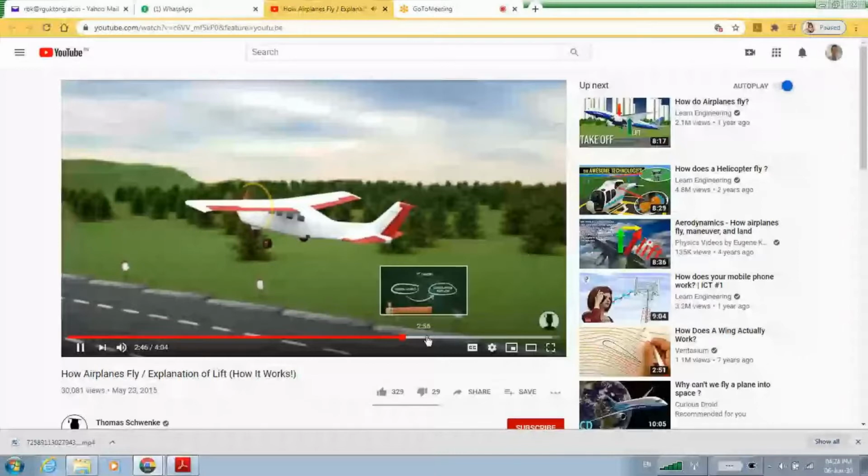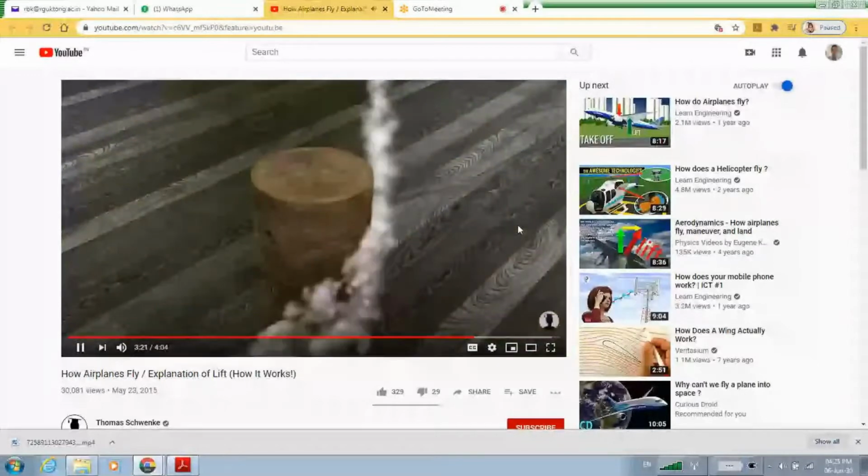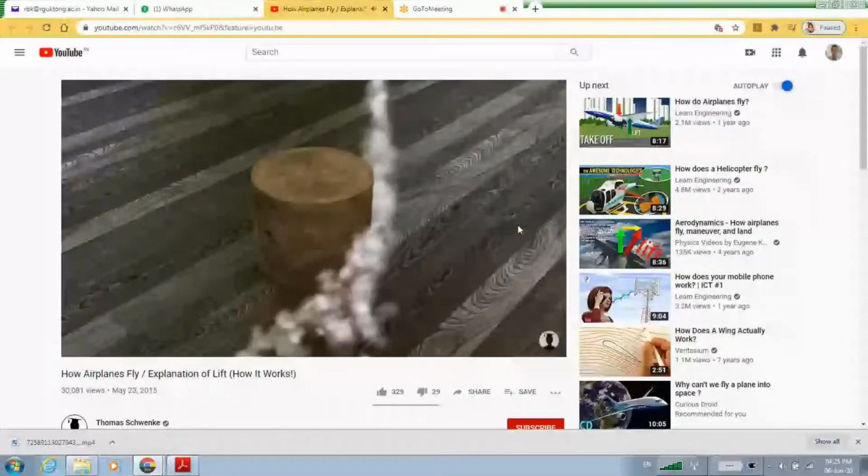Here, a key concept is the Coanda effect. The Coanda effect applies as soon as a moving jet of fluid meets a solid surface and follows this surface around the curve. This is also true for an airfoil. The form of the airfoil, however, is not as important as the angle of attack. That is, the angle between the airfoil and the oncoming flow.